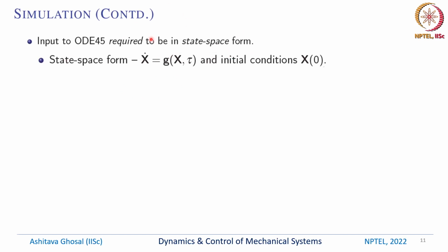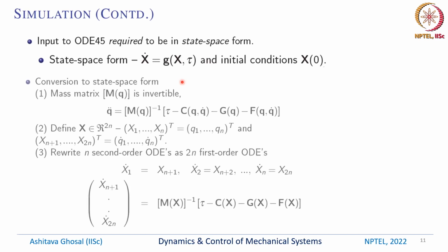This is what ODE45 requires you to give. Basically ODE45 requires you to give the right hand side of this first order differential equation. It also requires you to give some initial conditions, so we need to say what the solution is at t equals 0. All integration routines require an initial condition. Even analytically, if you want to solve or integrate, then you need some initial conditions.